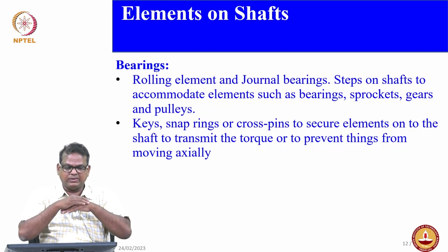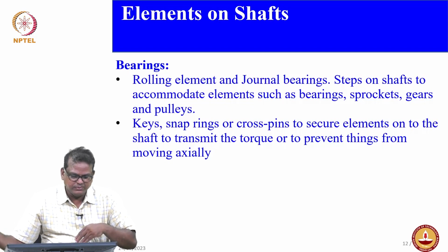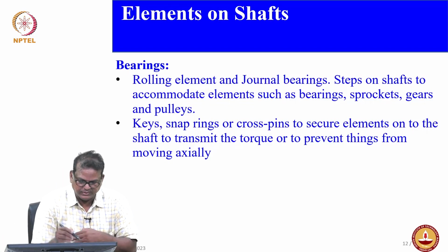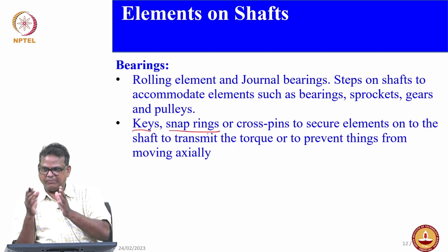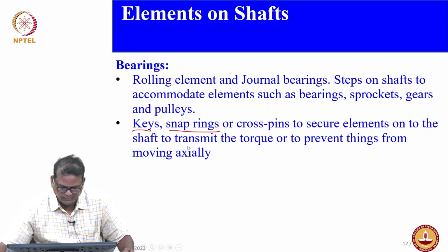So to avoid that, you will have a circlip, as we usually say in bearings. Keys and snap rings should be provided to prevent any axial movement.